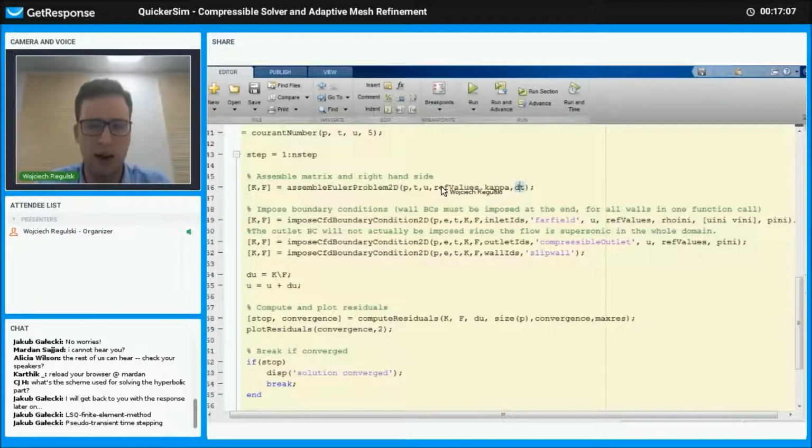So maybe not obviously. In our incompressible solver, we assemble these matrices regardless of the time step, and then we add the mass matrix, or introduce unsteady terms based on the mass matrix. Here we simply compute the matrix in the unsteady form initially. So it's just shorter and more convenient this way, especially since we do not have a truly steady state solver.